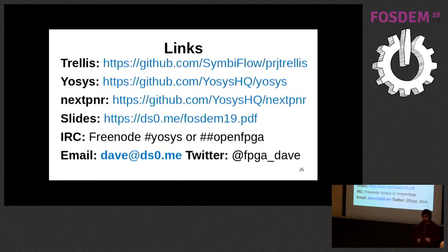What you can get from the vendor tools is the list of internal connections on a net, the list of connections between the fixed wires, the pips of a net, and the total delay of that net over all those connections. So effectively, you assume that each internal connection has a certain amount of delay, and you can split them up into classes. You say all connections of this class have this delay. Then you can build up a sum, and equate that sum